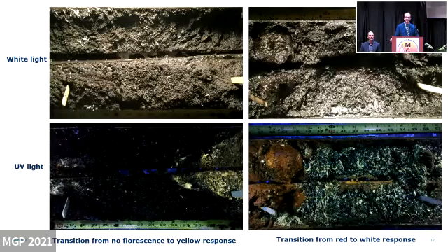And as you can see on this first core, there is not really any apparent NAPL visible on this section of the core, and the UV light validates there's limited fluorescence in that core. There is maybe a little bit of something unique occurring here, and the UV light validates that. And so in this situation, that would be an interval that you'd want to subject to a shake test or other tool to confirm if NAPL is indeed present.